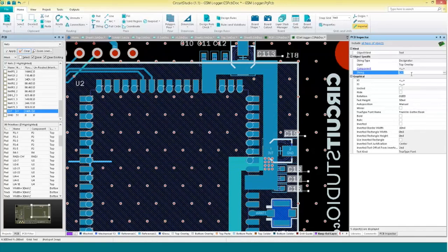And you can also enter that in with the curly brackets, old string equals new string. So that's just a little bit about the inspector panel and doing some quick global editing, and then some about the connectivity of multi-sheet designs.